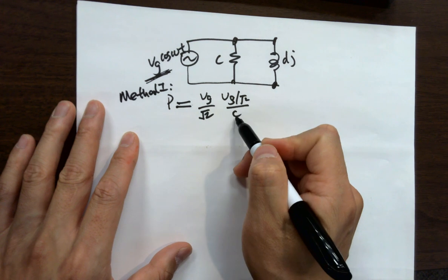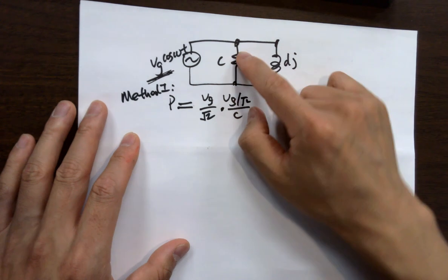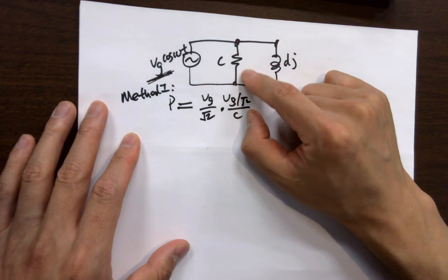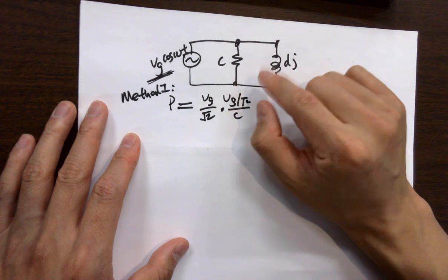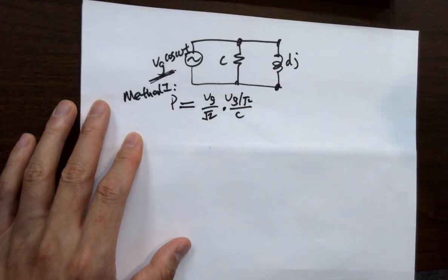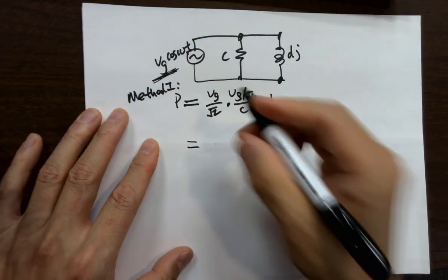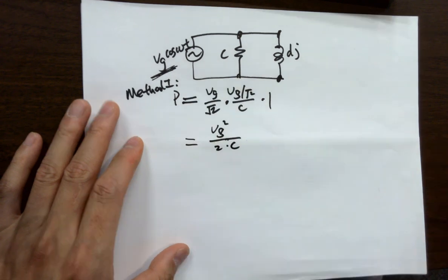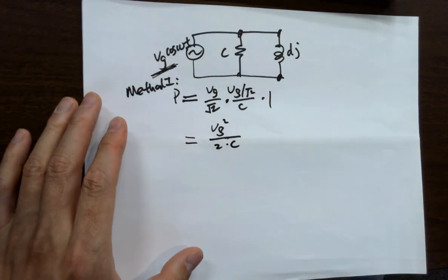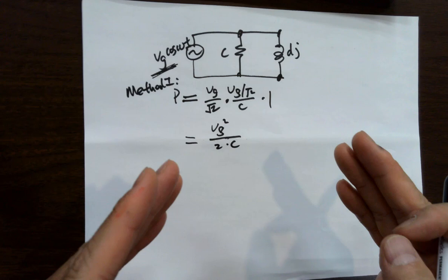So the resistance. VRMS divided by C is giving you the IRMS times, what's the voltage and current phase difference of the resistor? 0, right? Cosine 0 is 1. So what is the result? Done. So you can just focus on the resistor. You'll be fine.